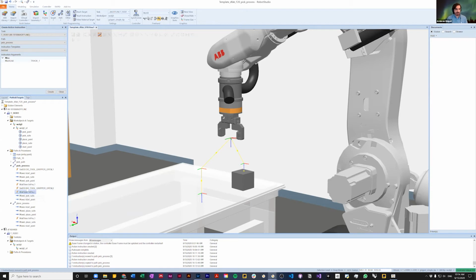And the same logic applies to here. So basically, instead of just making all these actions, I'm just going to Control-C and Control-V here. Oh, does it work? No, it doesn't work. Okay. I need to grab and drop this one here. I also copy paste this one, which is a gripper open, and put it here. So in the pick place, we open the gripper, we move there, we wait, close the gripper, we come back. In the placing process, we get to that position, we wait for a second, then we open the gripper and we move back. So it seems that in this scenario, we have the whole workflow done.